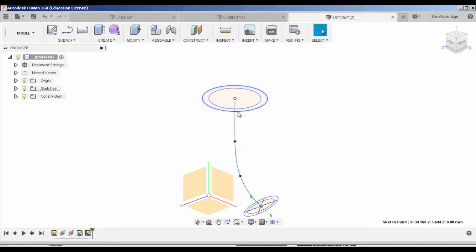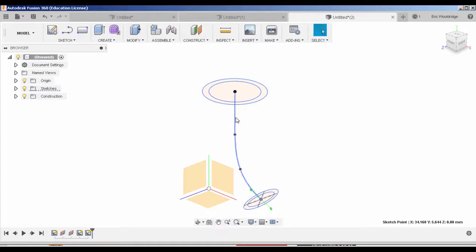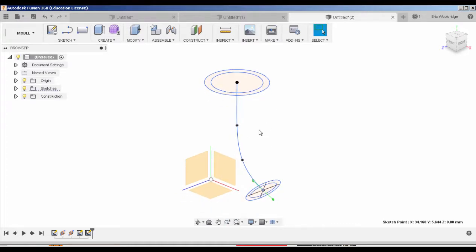Now you'll notice that I created both my shapes along the center line of this axis, which is fine. However, just so you know, lofts often have a hard time with that. So I'm not actually going to use this center line. I used it to create the sketch planes, but I'm going to create some new curves to work with. So check this out.